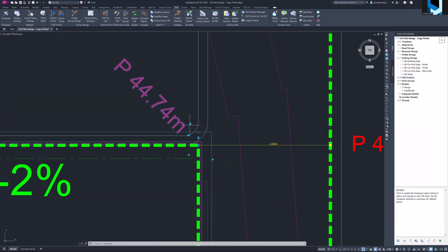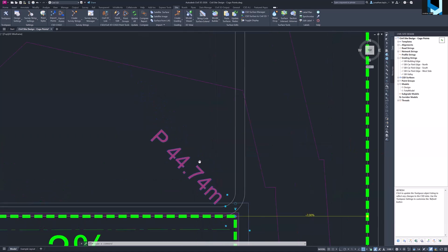For us, in the Autodesk world, we're going to hover over this blue circle. If that blue circle is not there, that means you have a Cogo point which is dead. It's not related to civil site design. So if you see that and there's no circle, you've probably done something like move or copy it. Copy is another one. Actually, if I just go copy, you notice how there's no blue circle for me to lock into? That's basically a dead Cogo point. It's a dynamic block, essentially, not related to civil site design anymore.